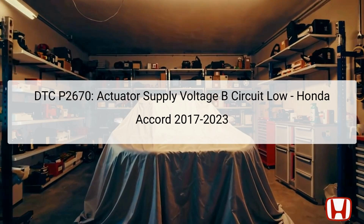Welcome to this presentation on diagnosing DTC P2670, which indicates an issue with the actuator supply voltage B circuit being low in the Honda Accord models from 2017 to 2023. This particular diagnostic trouble code, or DTC, is triggered when the body control module, or transmission control module, fails to receive appropriate voltage from the actuator supply circuit.